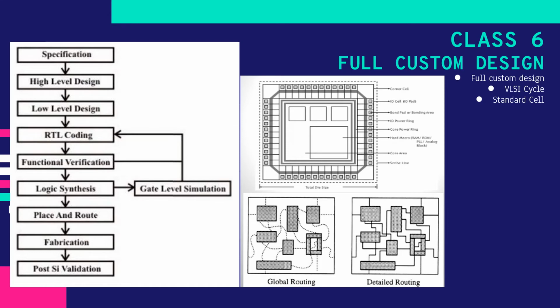In the floor planning and placement steps, your input to the floor planning is your set of blocks, both fixed and flexibles. Pin locations of the fixed blocks are done here, and the aim is to minimize area in order to make the circuit more efficient. The shapes of the flexible blocks are determined, and with respect to placements, the aim would be to minimize the total length of interconnects, which simultaneously reduces area.